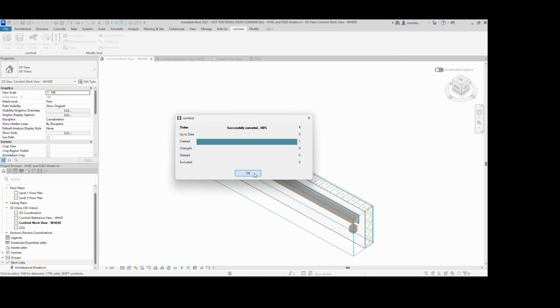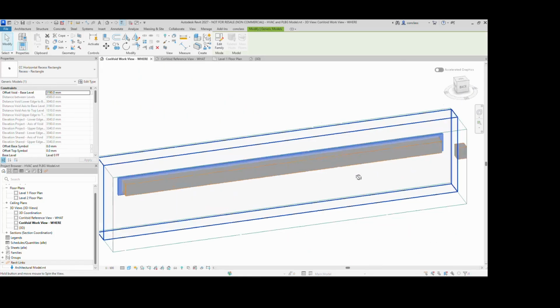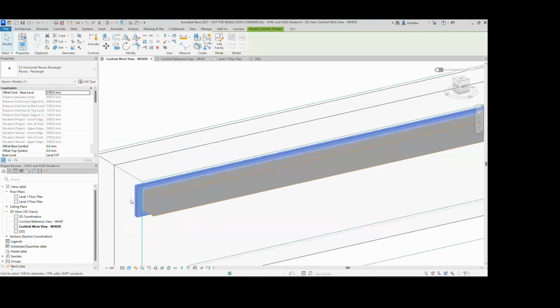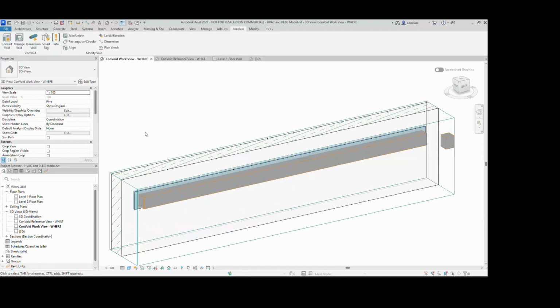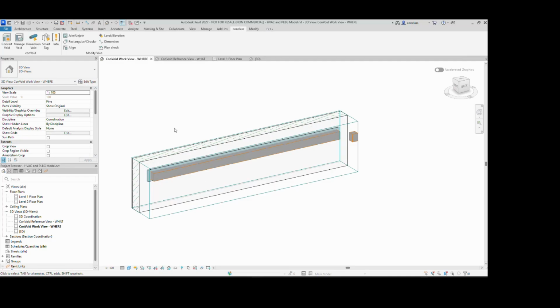And here we go. Here we have the recess based on the duct. This option can be enabled for vertical and horizontal openings, but consider that model inaccuracies often cause unwanted openings. So be careful using this option. If you need to, you can enable it. And if you're modeling quite well, then it's totally fine. So there's the option to do so.